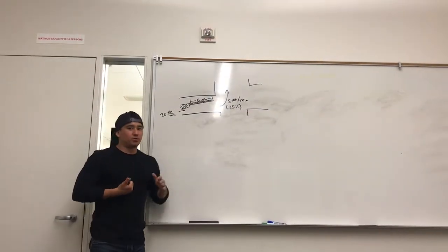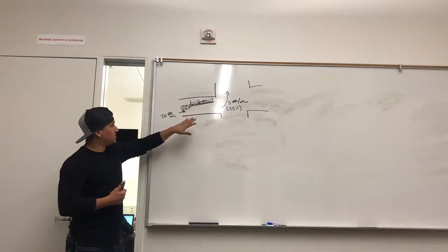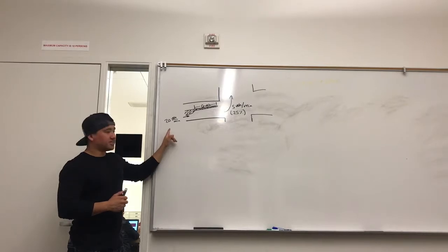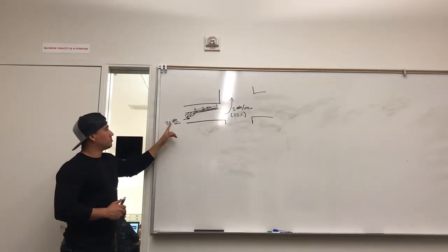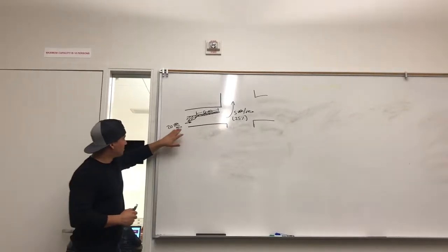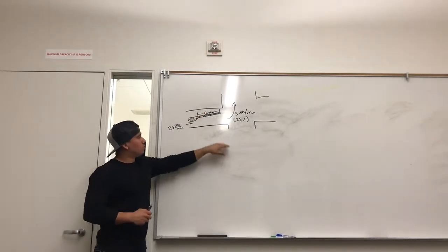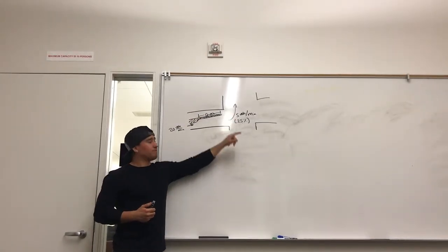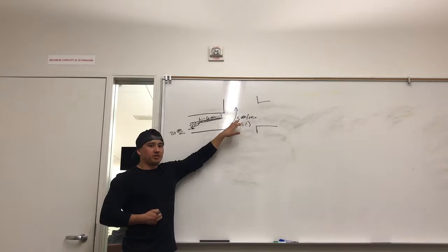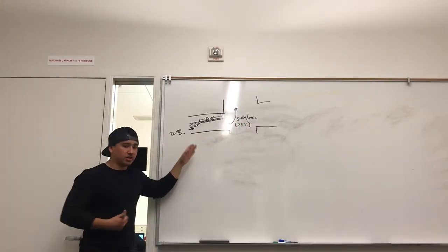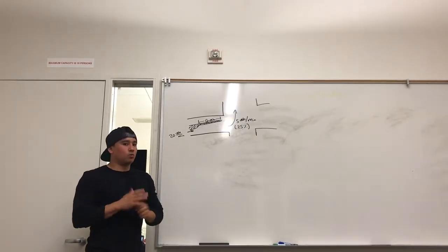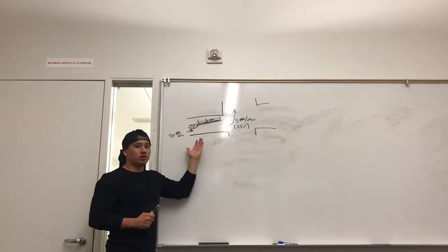So here's an example with the left turning lane at an intersection with a 6 vehicle capacity. And the flow rate at this intersection is about 20 vehicles per minute. And 25% of this flow will turn left, which is roughly 5 vehicles per minute. So if the capacity is 6, and not always will there be 5 vehicles that will turn left, we want to know the probability of spillback, which is if there would be more cars turning left.